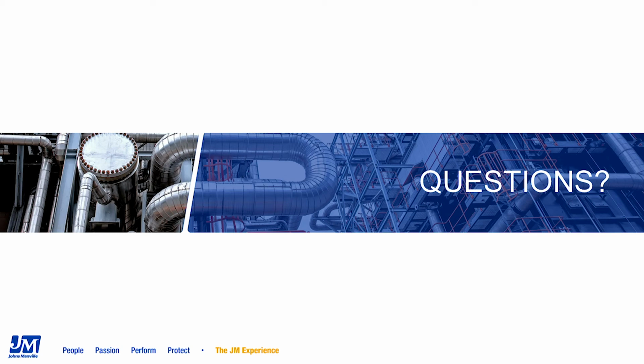Is there anything you'd like to add to that? I will say that fibrous insulations are probably the best option when you're looking for acoustical control. So any of our mineral wool products would be excellent for that. As I mentioned earlier regarding NRC ratings or noise reduction coefficients, the mineral wool products that we offer have pretty high noise reduction coefficients of about 1 or so. So if you're choosing a fibrous insulation, you'd be getting some decent acoustical control.